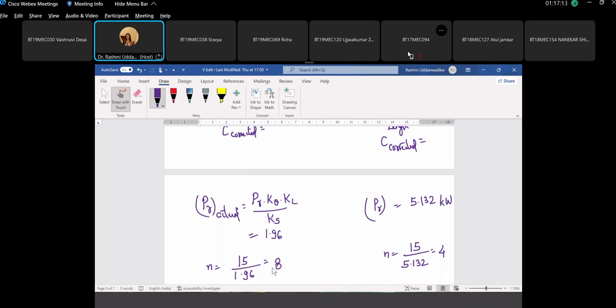Correct. Now you see which one is better. Number of belts 4 and number of belts 8. The size of the pulley, the width of the pulley, the cost, everything would increase with such a higher number of belts. And that's the reason: B cross section belt has a range of 2 to 15, and 15 is the extreme. We should not pick this. Picking C is better because the range for C is 7.5 to 75. So 15 is always a middle range. So we'll try to avoid the extreme cases, minimum and maximum. And so this shows how C cross section is better.